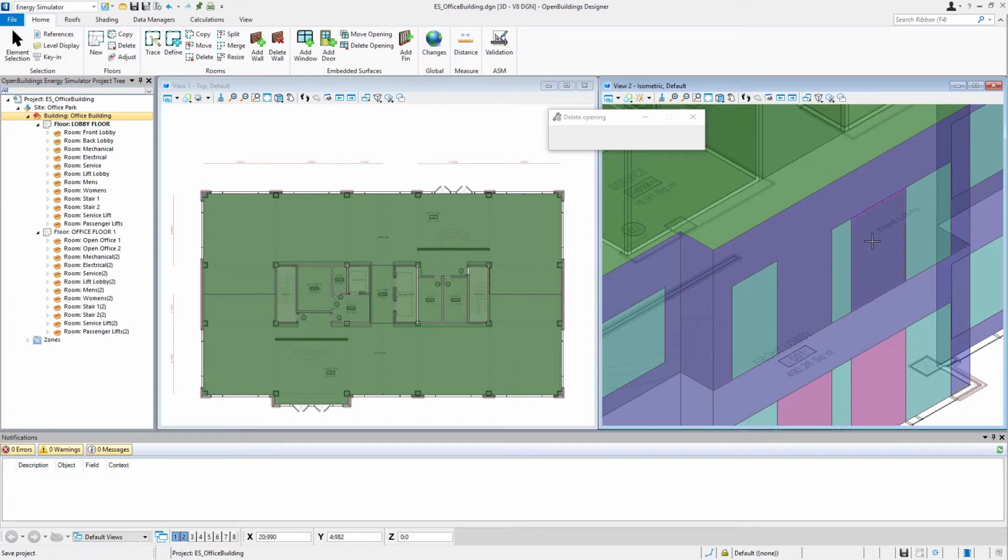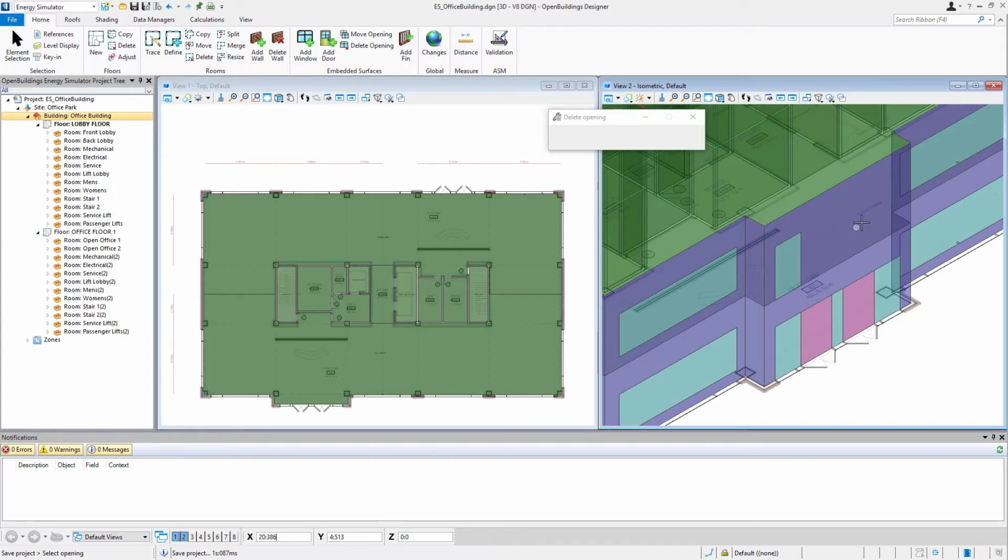We'll do the other door as well. And I'm actually going to do 2 of the windows. We'll leave this one here and we'll then modify it. So we're now going to modify this window so it matches the length of the opening below. So in order to get that length, I'm actually going to use our measure tool up here. We're going to just measure that distance.